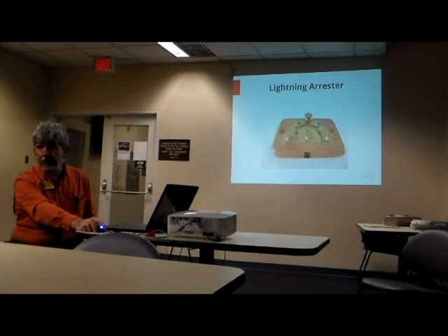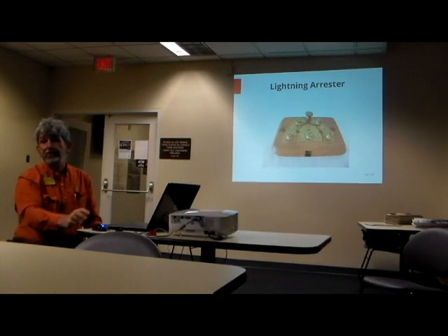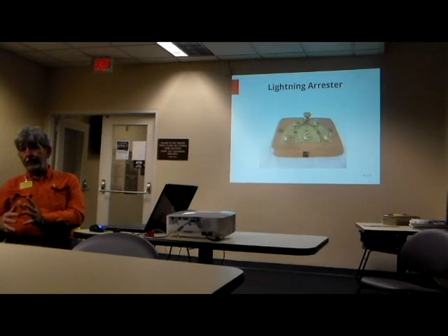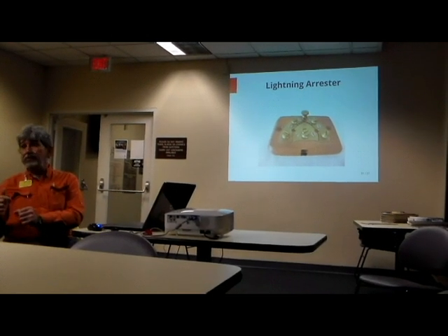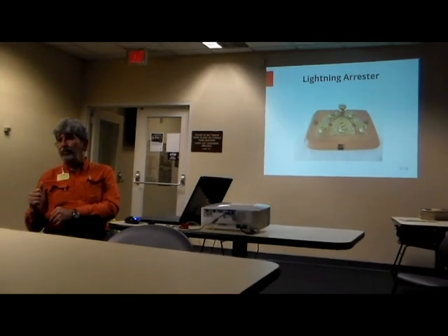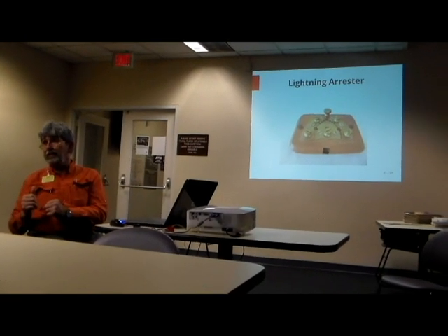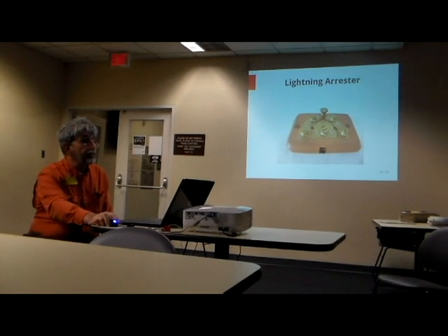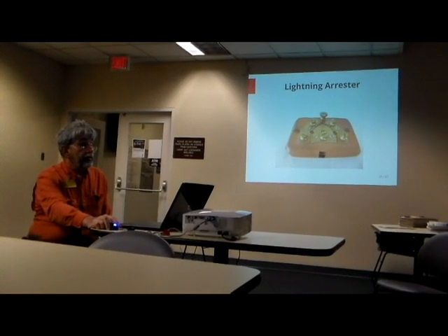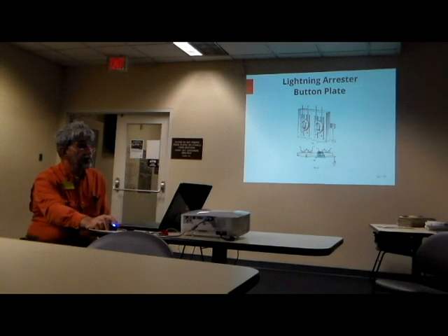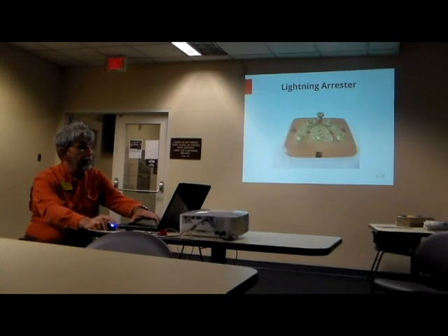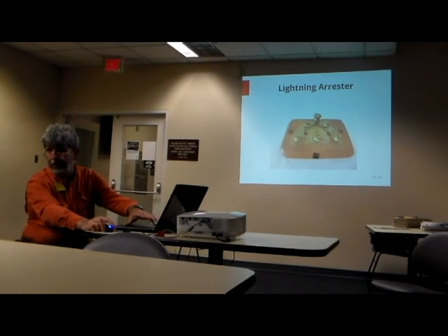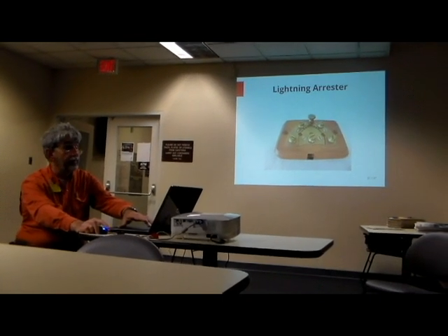Notice the sawtooth design in the edge of the plates. That was to provide a maximum length of surfaces adjacent to your ground plate that could discharge current. And the pointedness of the sawtooth design would cause the current to build up and break over readily and establish the arc needed for flow at that point. These three terminals down here are your east line, your west line, and your grounding electrode conductor that goes to the station grounding electrode.